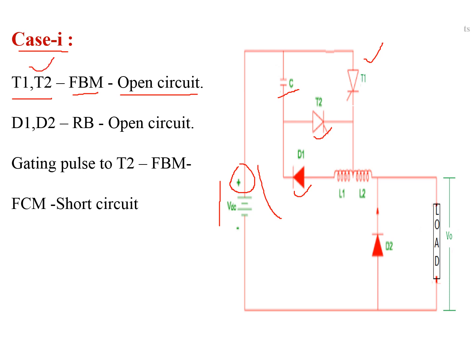Diode D1 is in reverse bias, which acts as an open circuit, and the negative polarity is connected to the anode of diode D2, so D2 is also in reverse bias and acts as an open circuit. That is the initial state of the thyristors and diodes before applying the gating pulses.